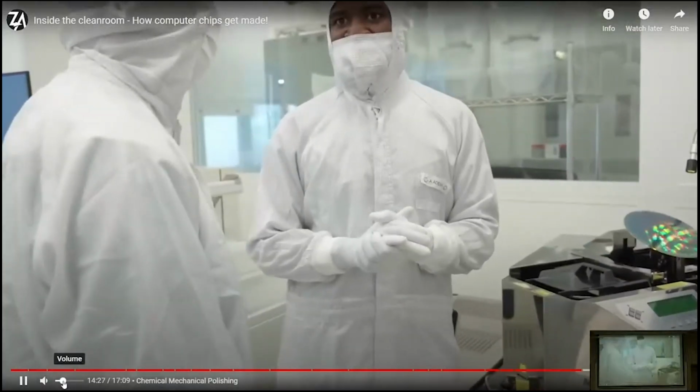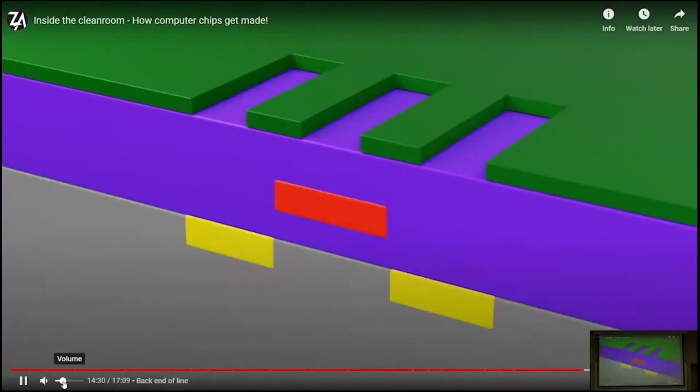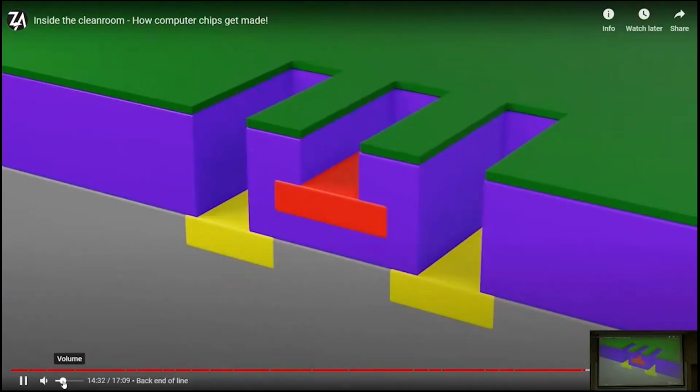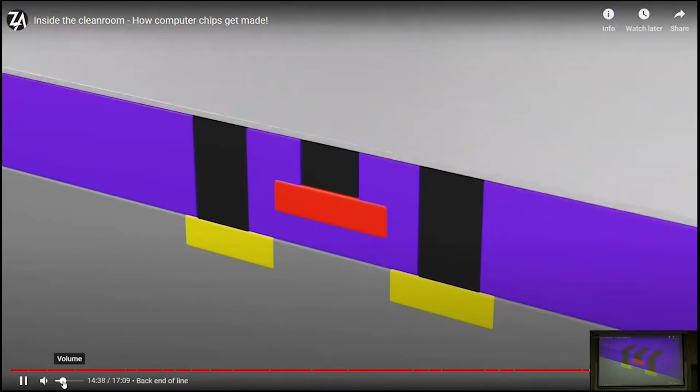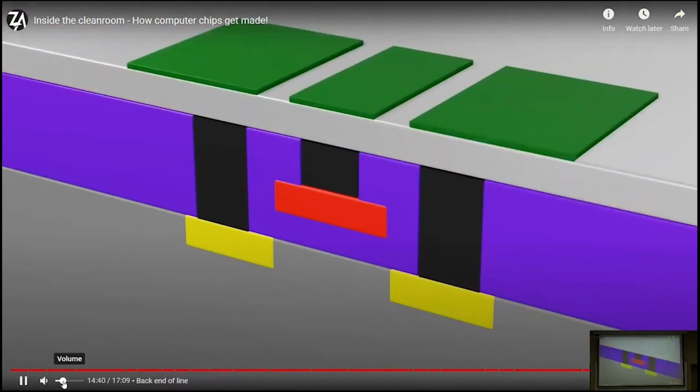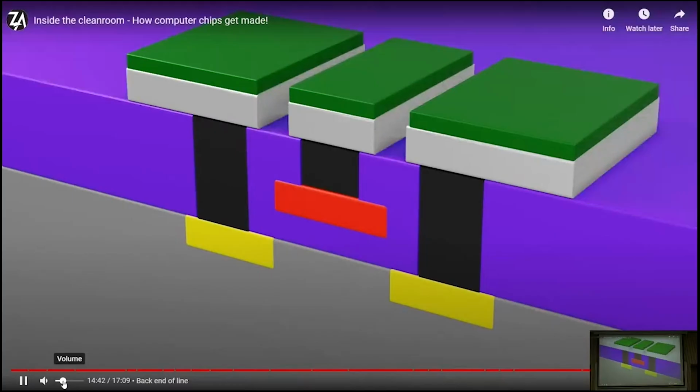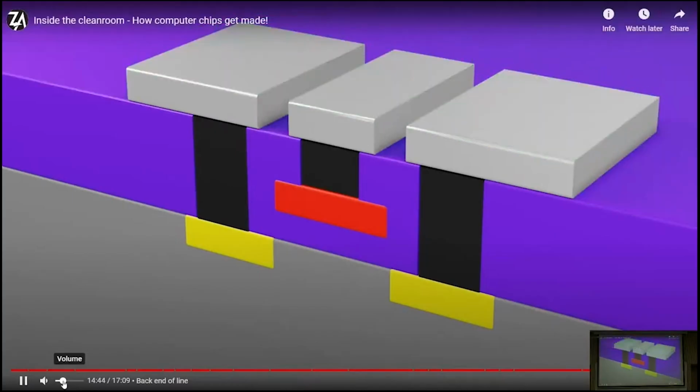Exactly. Our wafer then returns to photolithography, plasma etching, cleaning, then tungsten vapor deposition for the vertical connections, more polishing, aluminium vapor deposition for the horizontal connections, photolithography, plasma etch, and finally cleaning the developed photoresist. All of this has just taken us up to the first metal layer. IHP's process has 7 metal layers, so to finish the wafer, they'll have to repeat all these back end of line steps another 6 times.